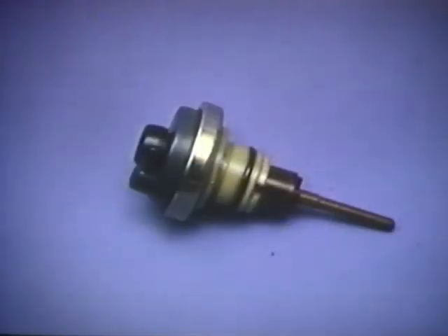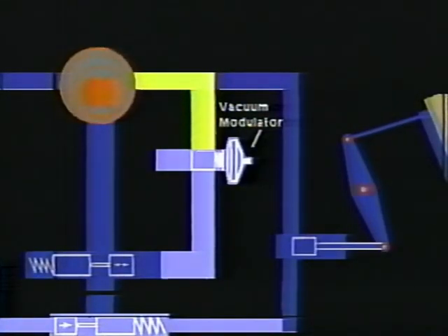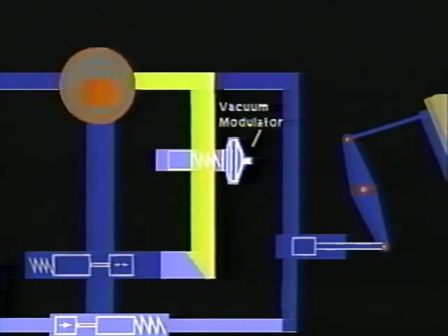To determine the actual load that the vehicle is under, a component called a vacuum modulator is installed on the transmission. It is connected to the intake manifold with a vacuum line and senses the intake manifold vacuum, and therefore the engine load. Depending on engine vacuum, the modulator positions a control valve within the hydraulic circuit. The valve will allow more or less hydraulic pressure to pass. This pressure is called modulator pressure.